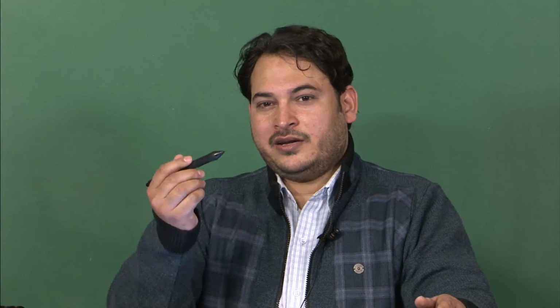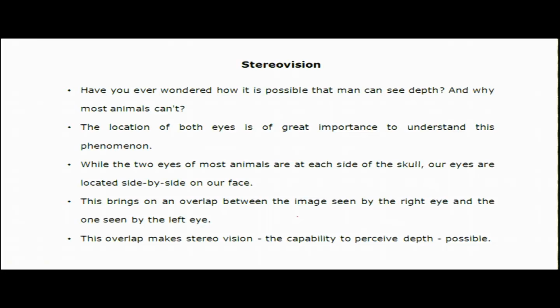When we see some area or some object, we can define in our brain what the height of that object or a building is, and what the relief over an area is. We get this ability on the stereo pair of these aerial photographs, when we see the left photograph with our left eye and the right photograph with our right eye. So it is the observation of the same area or the same point from different points of observation.